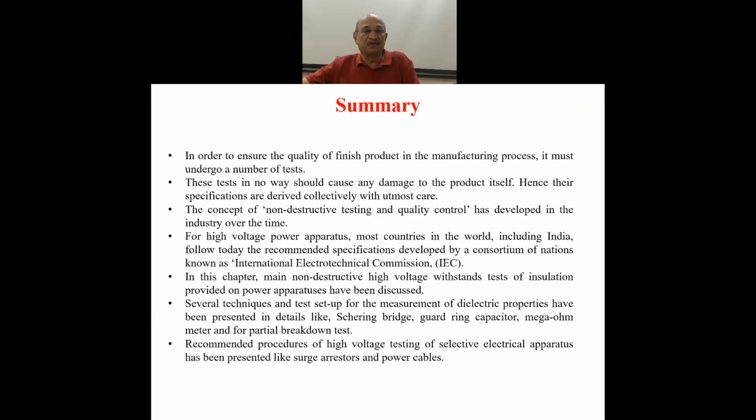That is, simple high voltage tests of AC, DC, impulse voltage, measurement of partial discharge, very important, measurement of tan delta, insulation resistance, as we discussed, by different apparatus. So all these reveal the quality of the dielectric, and you ensure the quality to get the desired length of satisfactory service of the apparatus.